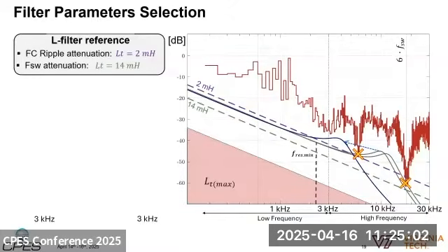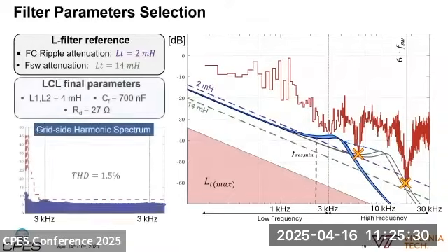the filter capacitor. And we can also verify, since we are using those daughter cards that David presented using low voltage capacitors that have 5% capacitance tolerance, what would happen if you have some tolerance? Are you going to cross the attenuation requirement? In case you do, then your filter may eventually not meet the requirement you established.